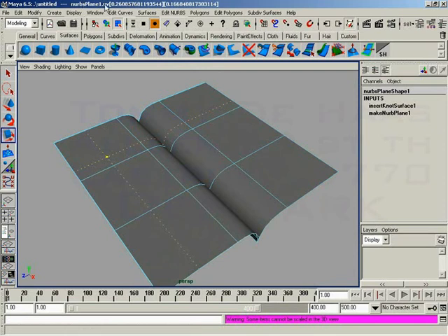NURBS plane 1.uv. UV. 2 pieces of information. The first number is the U coordinate. The second number is the V coordinate. Very nice. And we can use this, again, for marking specific locations, for grabbing tools and doing specific operations at a marked location, etc. Most of the time, you'll find me just using isoparm markers because seeing how you can drag multiple ones out, it's very handy. You can place one wherever you want, and you're only working in a given direction, and that's always really nice. Sometimes you don't want to work in both directions at the same time.